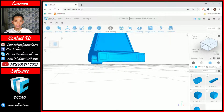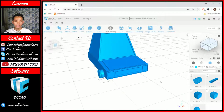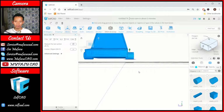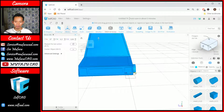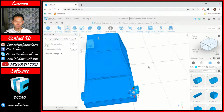We can copy these objects. Okay, you can click, and then I will use the move tool. We can press the Ctrl button, select this blue axis, and move to the right here. Okay, it will create a copy. I will move again to this point. Okay, make it the same.